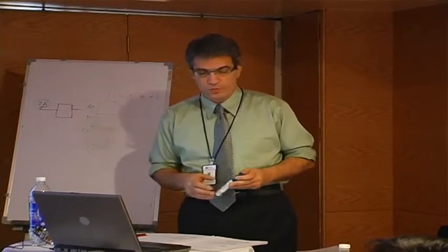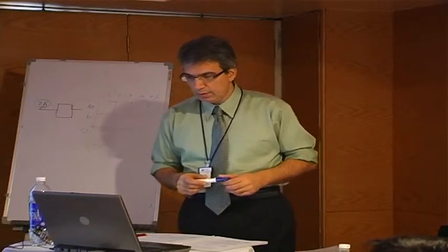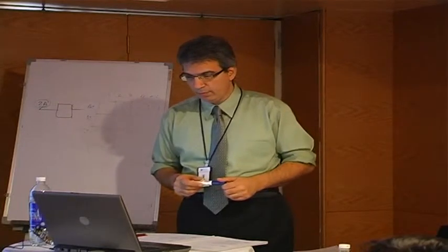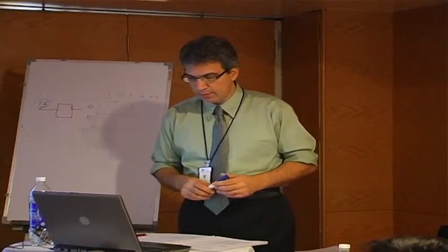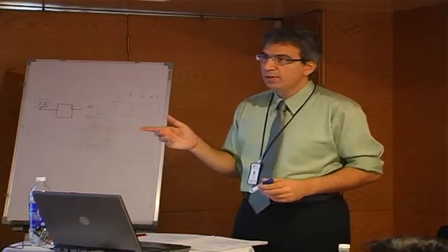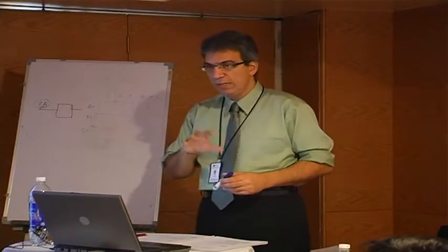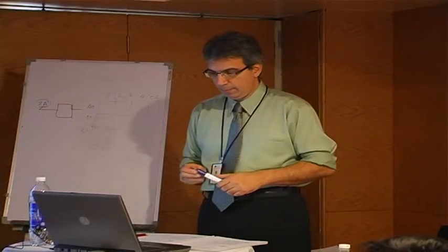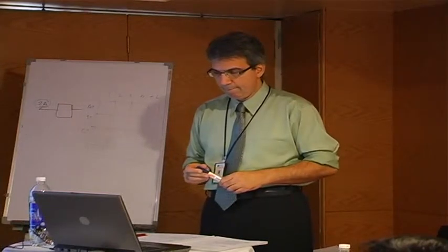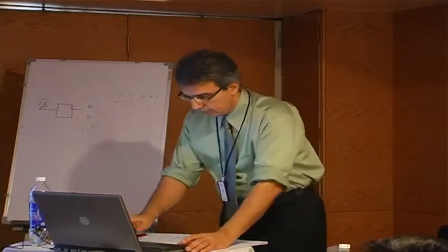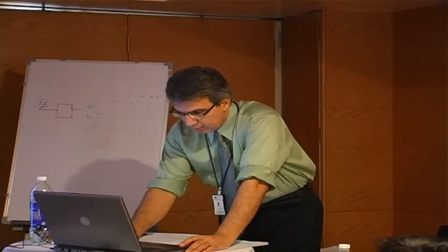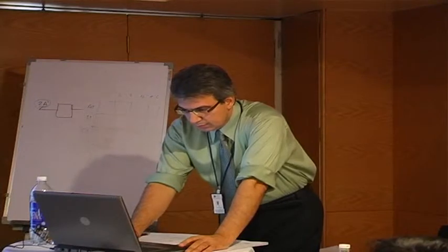Talking about sources of torque ripple, we can improve on the motor design, and we can improve on the control. And of course, the block diagram we have shown here proposes to make the outer loop significantly faster with an adaptive current reference. Now this simulation would be quite time intensive, so we have not included that, but that is something which can be quite easily incorporated here.